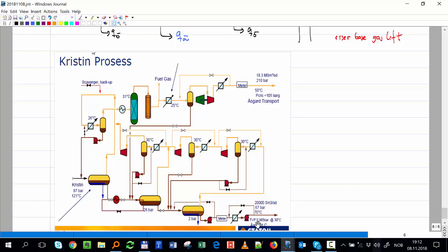And here you see this requirement of the true vapor pressure. The vapor pressure has to be 0.965 bar at 30 C. And you see the conditions. The water processing train is not shown here. The gas, again, goes through the cooler, then through the scrubber and the compressor. And then once more through the cooler, then compressor and so forth.